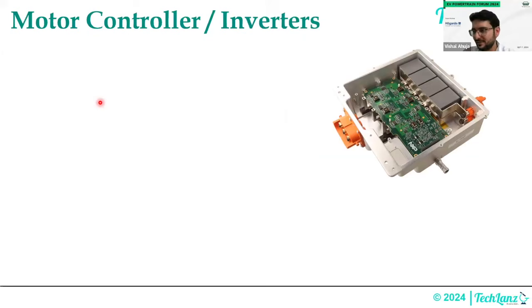Let's quickly cover the motor controller aspects also, right? We have gone into detail on the motor. In motor control also, since you will select your motor first, you should be thinking of the selection as a system as a whole, because as a system is what matters the most. We talked about it, some of the motors' control efforts are higher, right? Although they are cheaper, the controller will be expensive. So don't think standalone from a motor perspective. You have to think from a system perspective, including the gearbox. So a three in one combination.